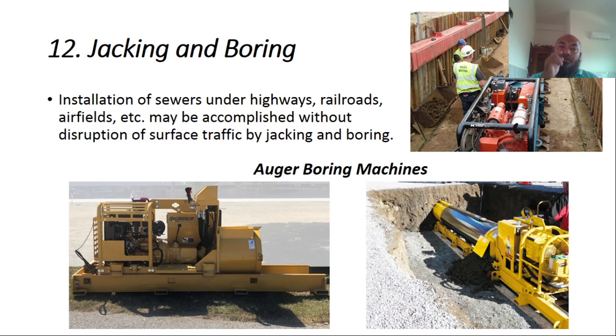Jacking and boring. Installation of sewers under highways, railroads, airfields, etc. may be accomplished without interruption of surface traffic by jacking and boring. So we can use this technology, this machine. This is the auger boring machine to do the jacking and boring.